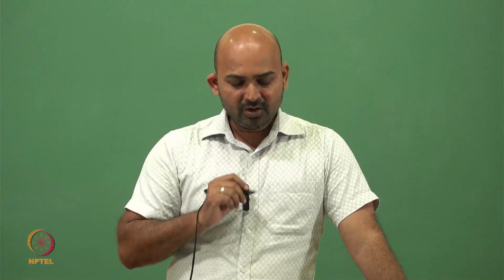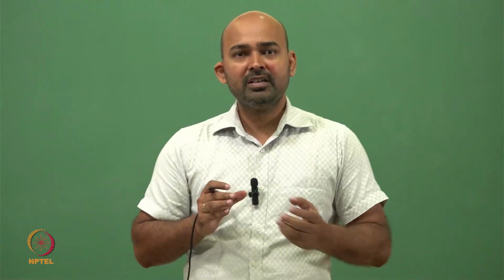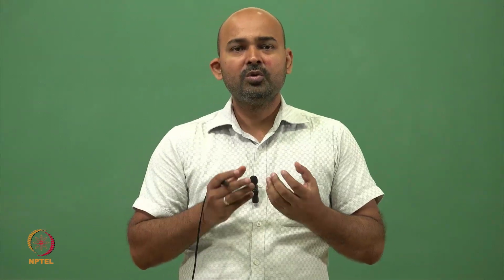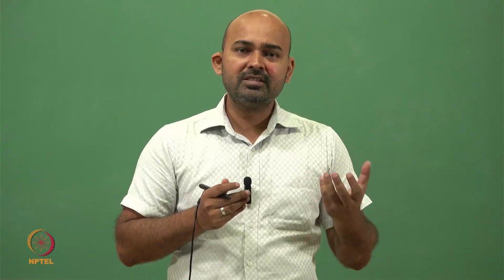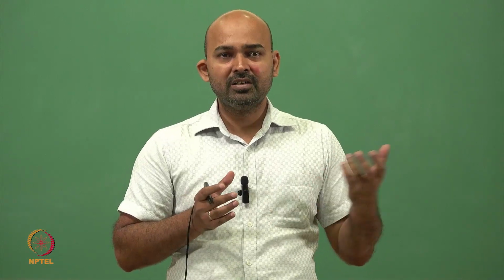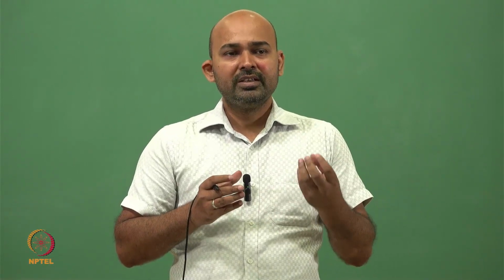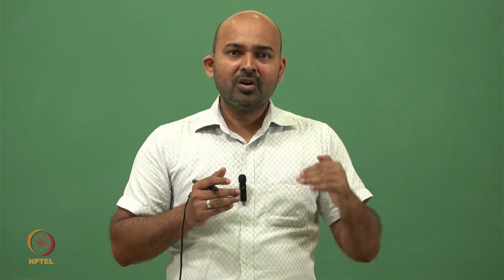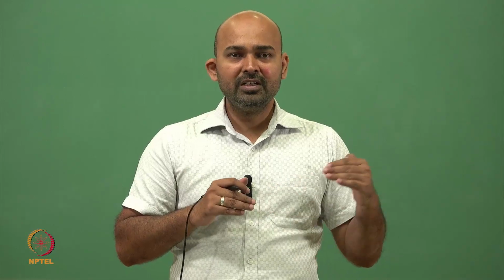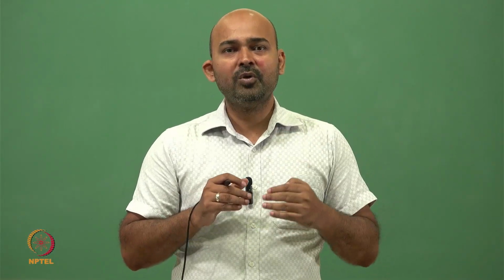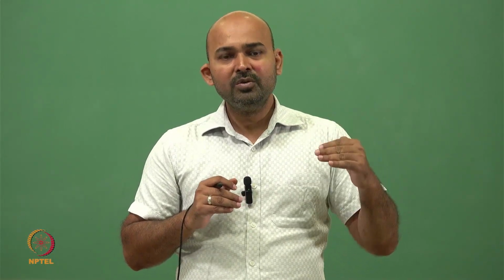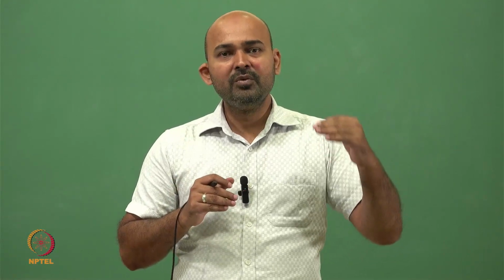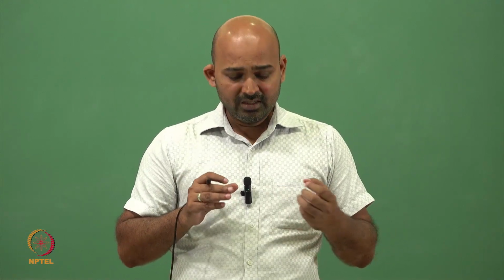Similarly, we have analog read. Analog read is the function which is used to read the analog value, because the sensors which are generally connected to the Arduino give the output as an analog signal. An analog signal does not necessarily need to have only 0 or 5 volt. The voltage can be in between as well, so that is an analog signal.